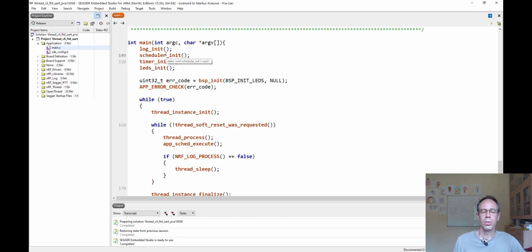The scheduler is a little bit confusing at the beginning. We need this because we have event-driven programming here. This means when we push a button, then an event is called, and a callback function is called. And when we have something to compute there which needs a little bit more time, we are also blocking other interrupts with the same or lower priority. And of course we don't want this, because maybe we have a lost packet or something like this because the stack is also hanging.